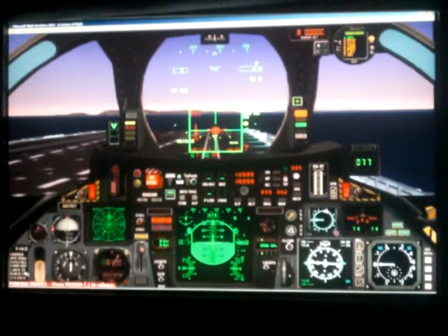So basically this is it. You got your standby altimeter, standby airspeed gauge, standby attitude ball, and a radar altimeter over here. Speed brake toggle off and on here, and lastly what's cool, you'll see the speed brake light comes on, speed brake lights illuminate up here too, but on the left is a little checklist placard I made for landing it. Approach and carry at 135 knots with full flaps and your speed brake out is basically the procedure for this.